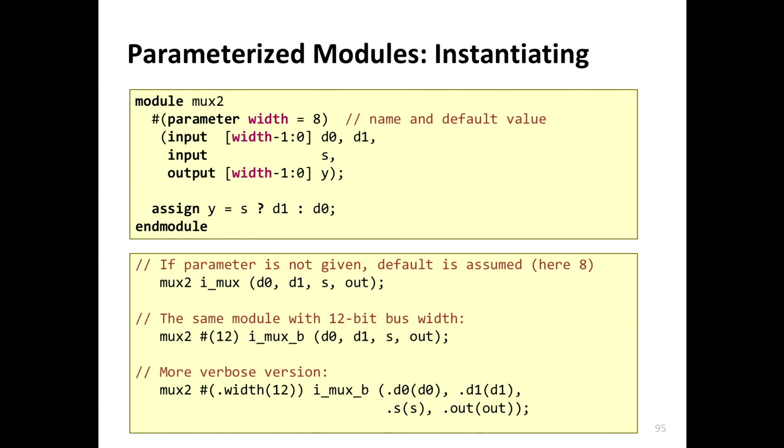What is going to be important here is that if you come back to this module and want to change the 8 bits to 16 bits, then you don't have to go all the way and find every input and output signal and change 8 to 16. It's just to make it more convenient, and it's going to be converted right at the synthesizing part, and then it's done. That's it. But input and output are actually going to be hard wires.